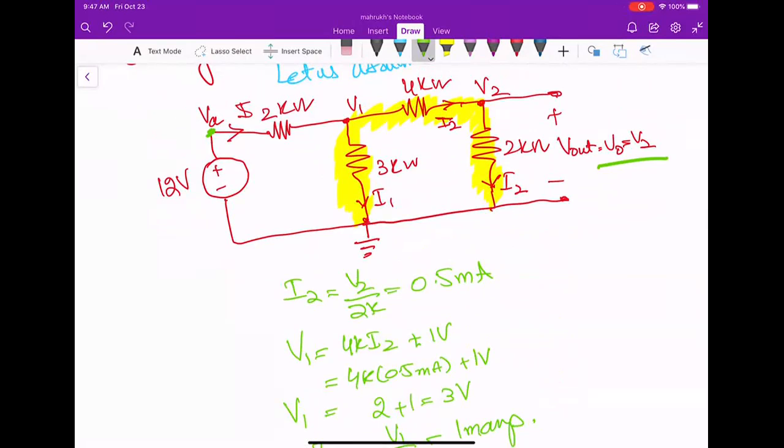I times 2 kiloohms. Okay, anyone else? VA minus V1 equals I times 2 kiloohms. Wouldn't it just be 12 volts? We know that it's 12 volts. I'm just checking through my calculation that it's 12 volts or not. So now I know my I, right? I want to know, using my calculations, forget about 12 volts. Using my calculation, I want to know how I can calculate VA.